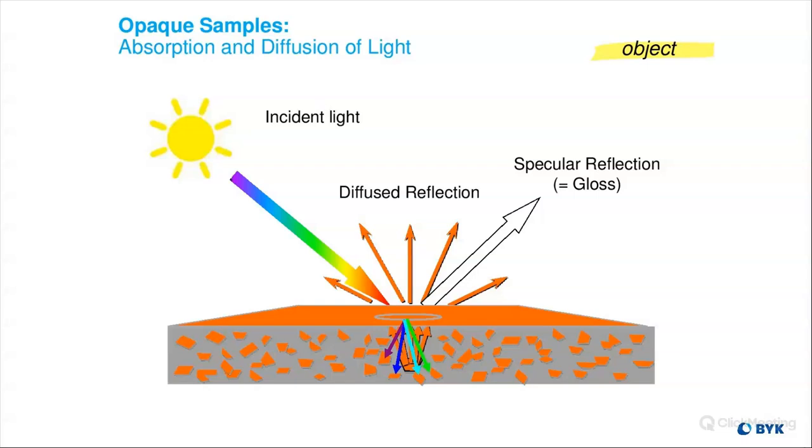When you're looking at those measurement geometries for gloss specifically, not for color, but just for gloss, a 20-degree angle gloss meter is going to send light at a very sharp angle down, reflect off the sample, and reflect back at a sharp angle. If you have a very glossy surface, you can replicate this by taking your phone out and looking at it from a 20-degree angle. You're going to see a clear reflection because it's a very glossy surface.